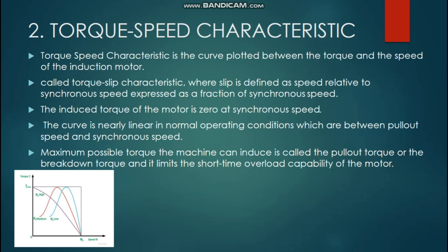The torque speed characteristic is required in order to predict behavior of induction machines in electrical motor drive. It should be measured as accurately as possible, while the selection of which method to apply depends on the characteristics of both the machine and the testing facilities.